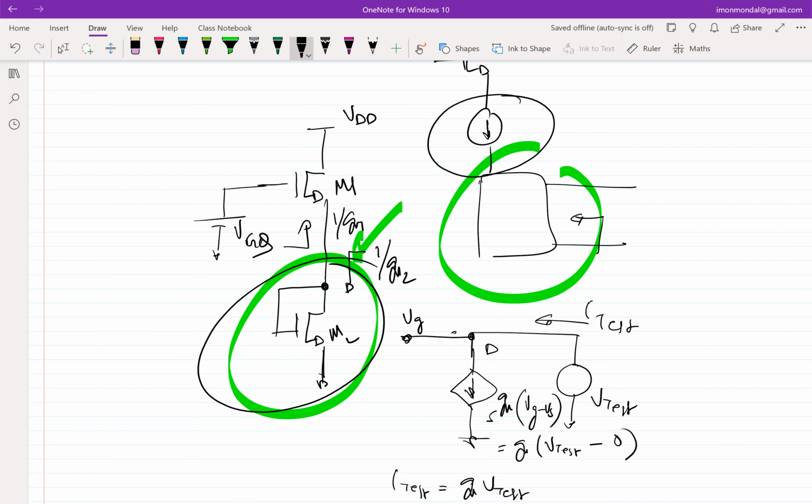Okay, so what else can we do? A transistor has three terminals, out of which 2 are conducting. You have eliminated the source, because looking into the source, you get 1 over GM. What else remains? Gate you cannot, because no current goes into the gate. So if you connect gate to drain also, it's not working. So what remains?